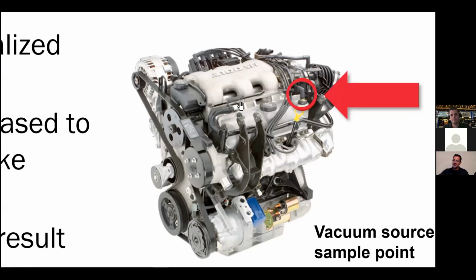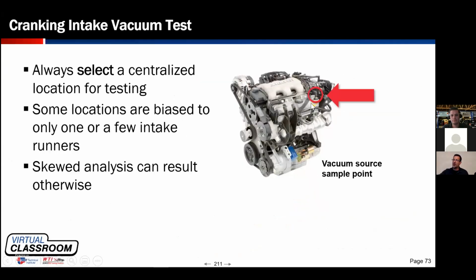Doesn't it make sense that I'm going to be taking off only this valve cover? I'm going to loosen this bracket so I can gain access to the fasteners, but I've got a little 8mm bolt here, and one here, and one here, and one here. Is there any reason to pull off everything? Right? We just want to get to that rocker.